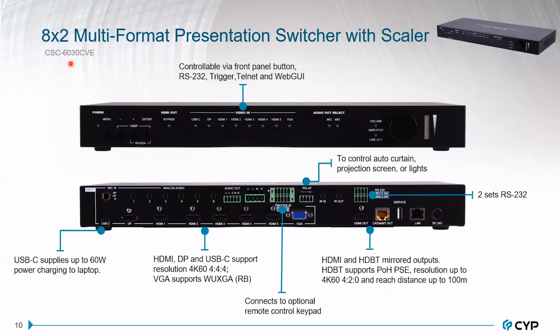The CSC 6030 CVE is the 8-to-2 multi-format presentation switcher with scaler. USB-C supplies up to 60-watt power charging to the laptop. The HDMI, DisplayPort, and USB-C inputs and HDMI output support resolution up to 4K 60 4:4:4, and VGA supports up to WXGA.